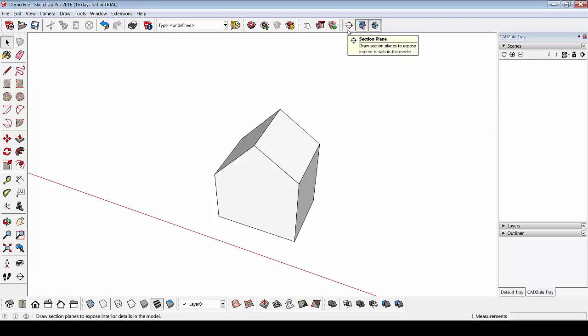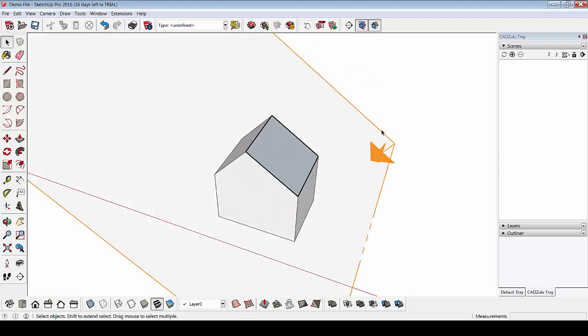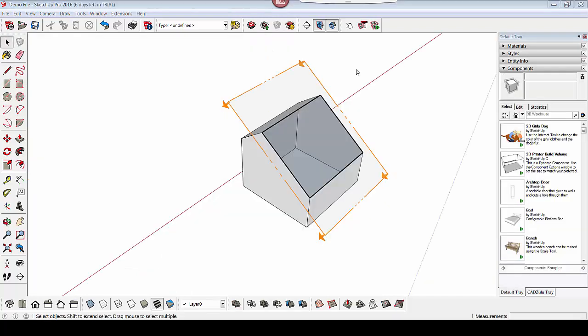SketchUp 2016 will now recognize intersection points with hidden section planes. So if you do apply, say, a section cut over there, if I just hold down Shift, it will keep that angle. So I can just slice through the model. And if I now click, say, on the line tool, you can see it actually snaps to these intersection points as well. In 2016, this will now also work when you hide the section plane, as you can see there.